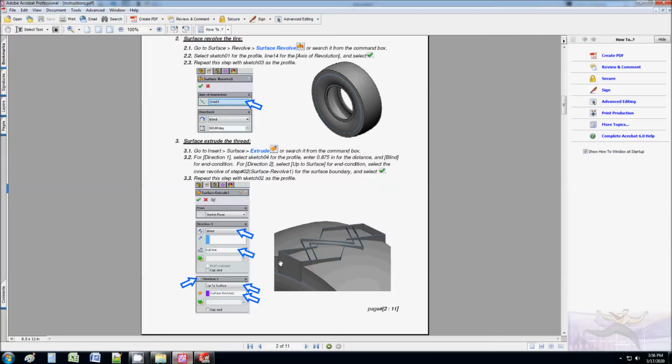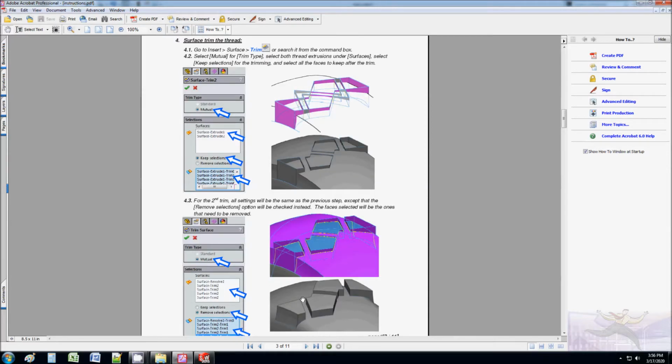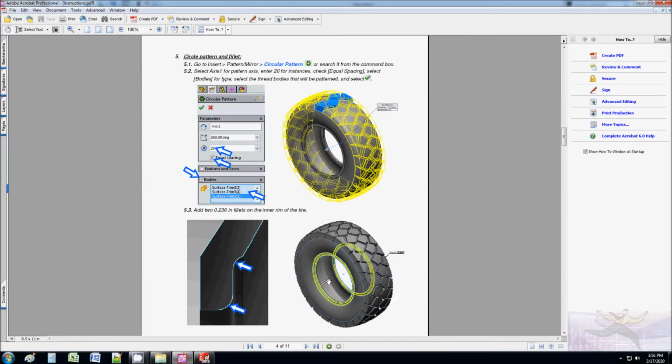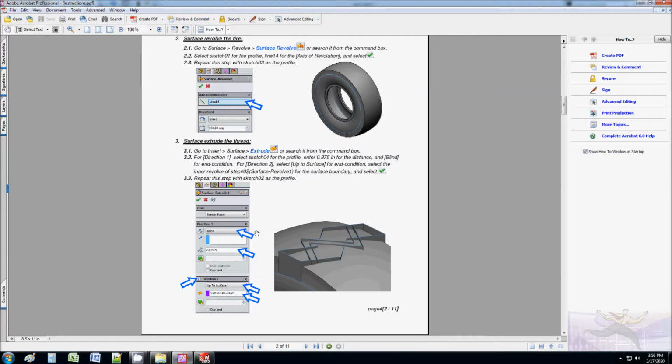What you've got to understand is our procedure, our approach. In regular solid modeling, the way you would achieve that is just to draw 4 rectangles and extrude that, and you're done. But with surfacing, the approach is different. We're going to have to build the excess surface. We're going to have to trim. We're going to have to knit. We're going to have to do all these different steps just because it's a different technique. It's a different tool set.